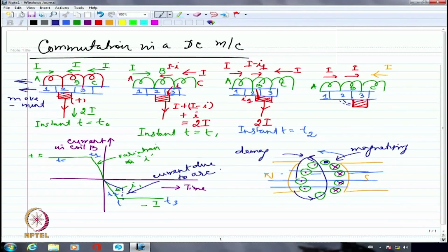If the wear and tear in the machine is quite large, then also you may see it, because normally we expect that the brush has to make a good contact here. By chance, due to wear and tear, the brush's edges may be rounded like this. It's not making a proper contact. Then also the contact area decreases, because of which some portion of the current has to flow through the surrounding air. So you might see sparking in machines which have gone through years and years of life.